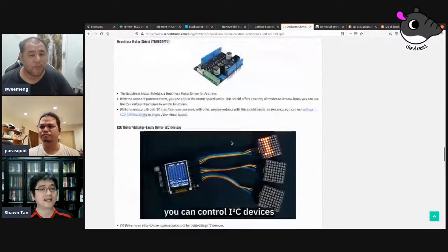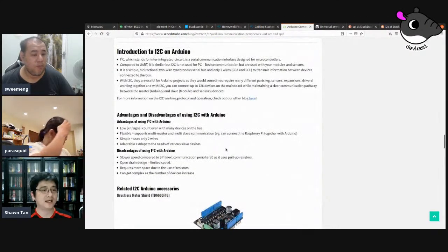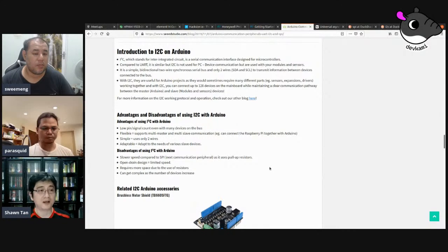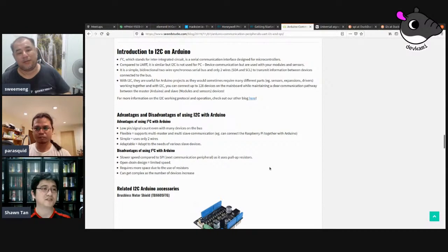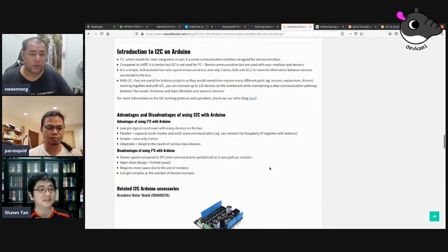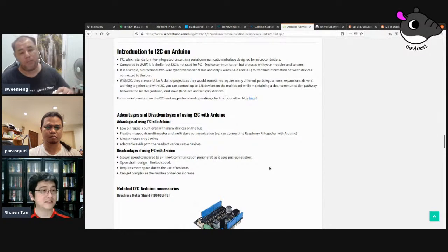Then the next fastest, we go one step down, is I2C. With basic I2C, we're talking about 100 kilobits, slightly faster, 400 kilobits, super fast. Even the fastest I2C that is going to be used by hobbyists will be only in the range of maybe 1 to 4 megabits. That's the kind of speed we are talking about on I2C. But when you go and look at the sensors, most of the sensors are running at the original version 1 I2C speed, which is only about 100 kilobits. That is pretty much the speed.